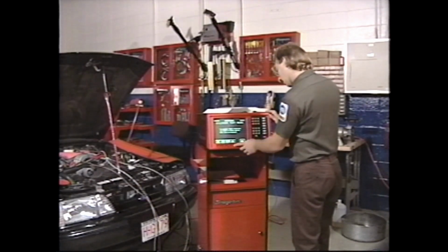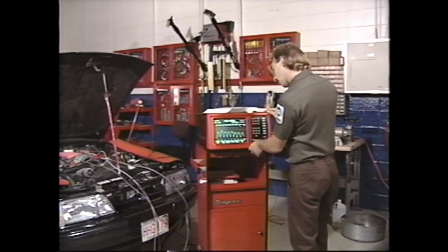Are you looking at a problem in the ignition system or in the cylinder's ability to build compression and produce mechanical power? Could the problem be caused by defective sensors or a faulty control signal? The scope gives you a variety of related tests so you can look at pieces of information from different angles. You can go from one test to another in any order you choose, and you can quit a test at any time. If you're not sure where to begin, start with a go, no-go test like the vacuum waveform screen in the cylinder test menu.